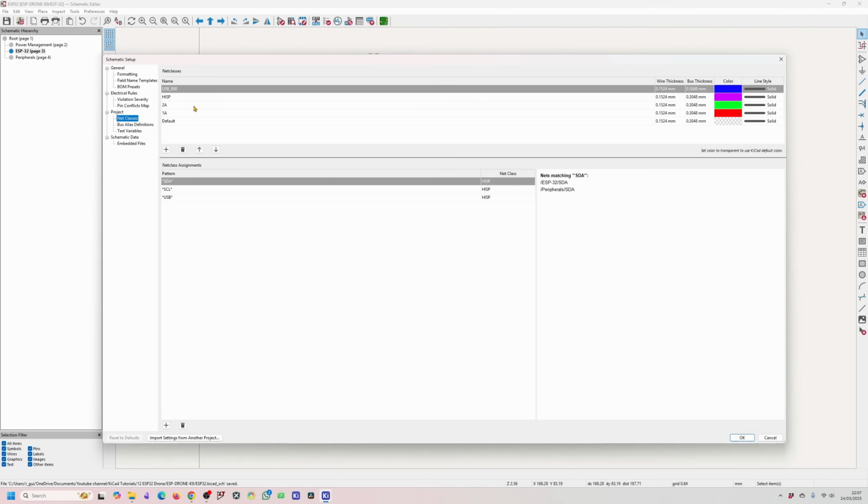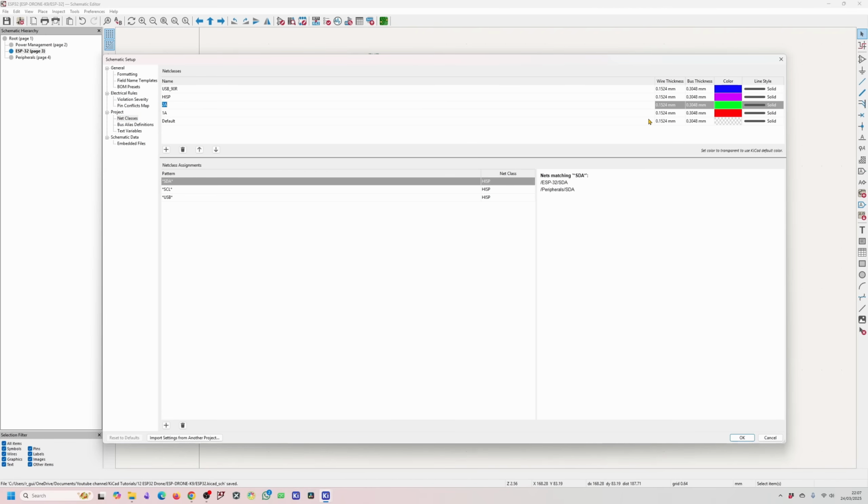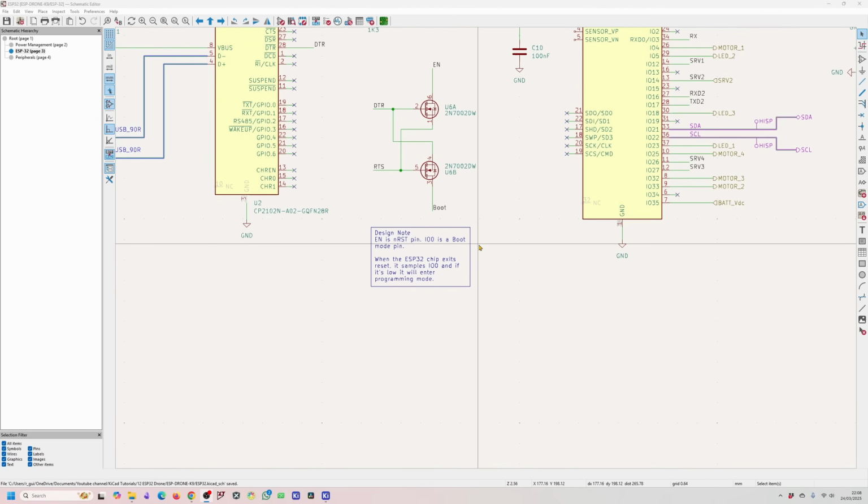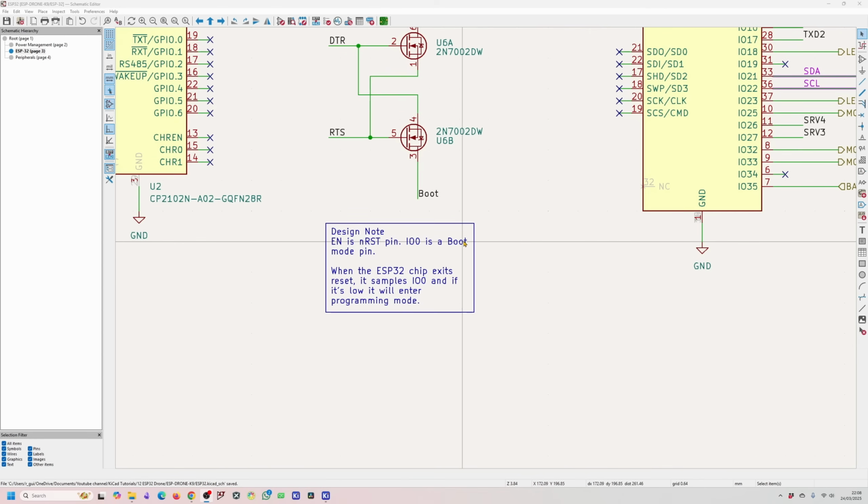The other two are kind of self-explanatory. They're basically denoting high current paths in the circuit itself. So 2 amps and 1 amp. For the PCB design rule, the main thing that's going to dictate is the track thickness. Now, sometimes the voltage drop might be important as well. Then you can communicate those types of rules with a design note as well on the schematic. In the last video, I did say I'll go through design notes, but I think this video is going to be long enough anyway, so I'll leave that off for another video. But essentially, this is what I mean. It's basically placing a note on the schematic itself that conveys some message to either yourself or someone else that's going to be looking at the schematic or the PCB design.